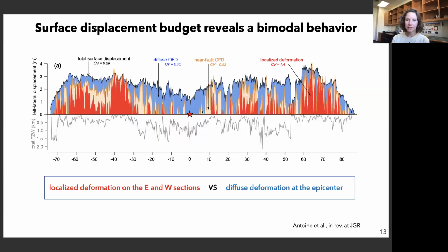But what I thought is that where there is the place of the hypocenter, where the rupture actually has lower slip and has a smaller velocity, it doesn't manage to rupture and propagate all the slip up to the surface, and so it does shallow slip deficit, or yielding. And it takes the rupture a few tens of kilometers to develop fully and have more slip, more velocity, and then only can you localize all the deformation on the fault.